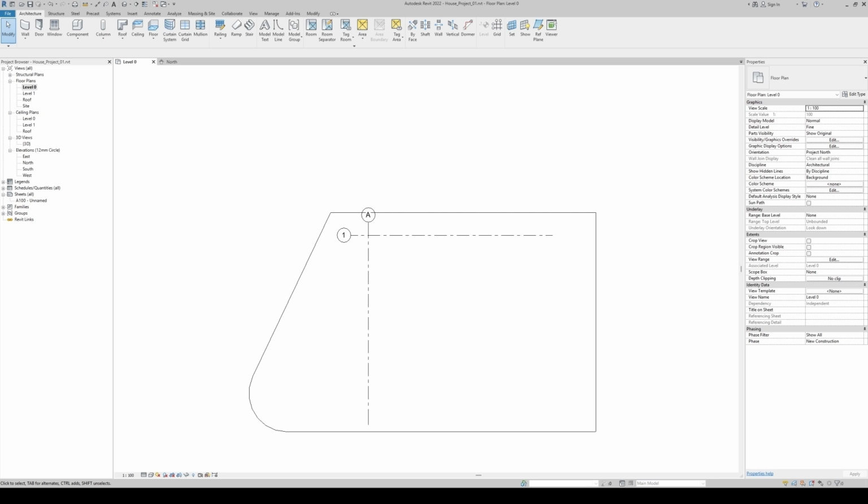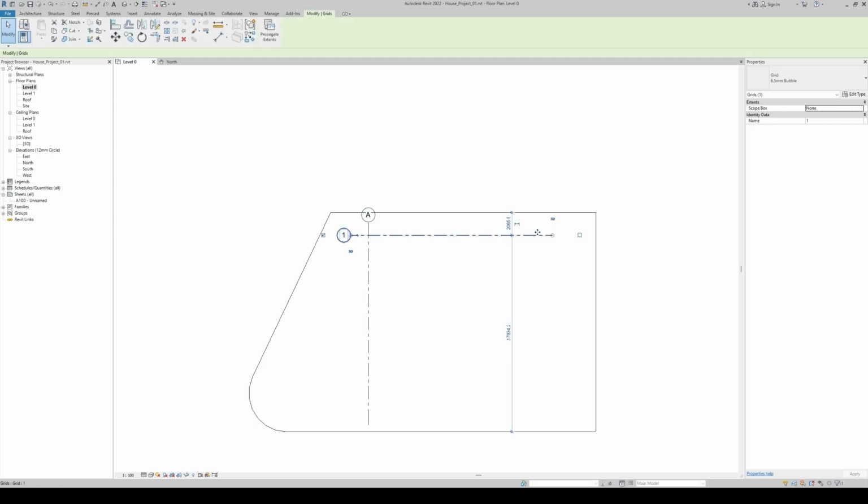And once we know our building geometry, then we are going to add more grids. You can move and adjust your grids as required. Let's suppose we want to reduce the size of this grid. Then make sure you select this bubble at the end, and here you are fixing the 3D extent. Let us select the bubble and drag the grid to reduce its size.